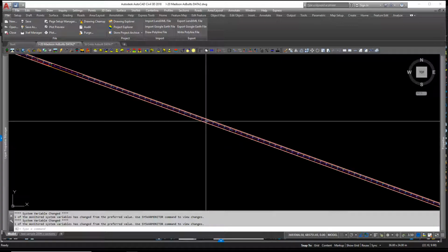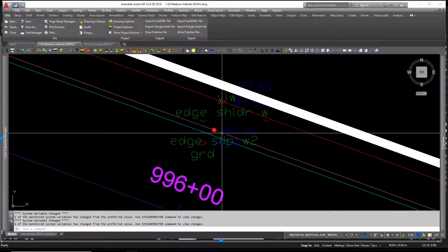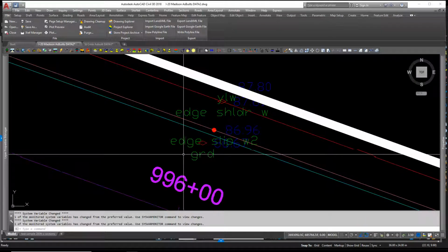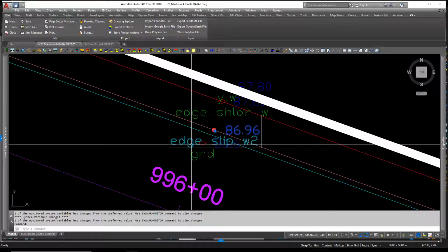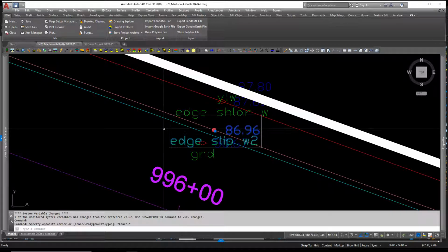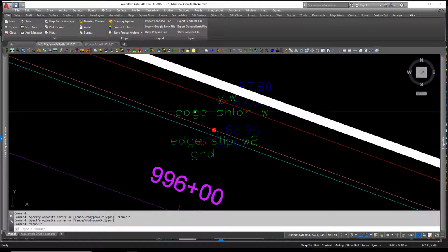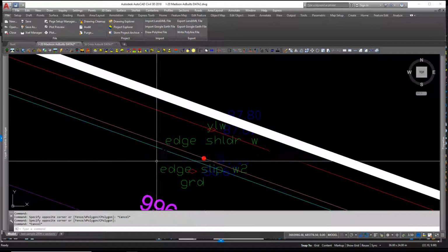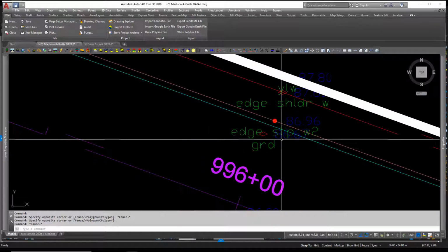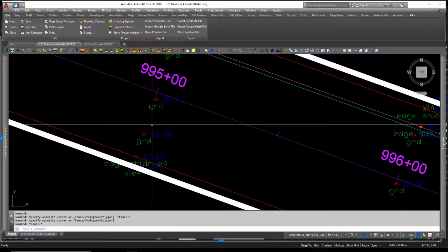These are shots taken on a much longer stretch of road, and you can see that they were pretty well P-coded. A lot of times we'll get these where, like all of us, we'll forget to change the name of something, and you'll have a bunch of points that are not correct. So we'll oftentimes go in and change these descriptions to make them match exactly what was happening.